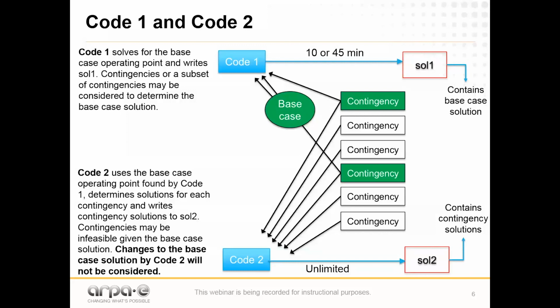So the formulation naturally allows for the ability to adjust to the fact that you expect all generators to follow their participation factor, but some do not. And for the ones that do, there needs to be some sort of an adjustment because their participation factors don't add up to 1. And that's the delta K.